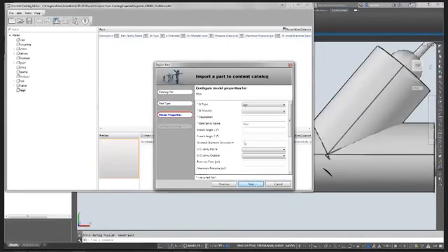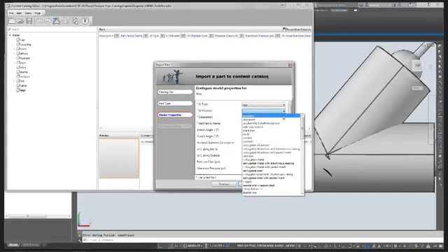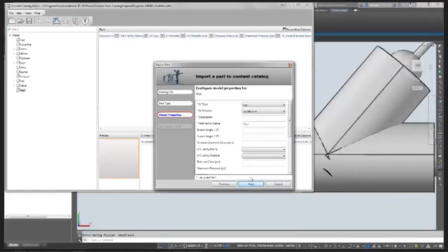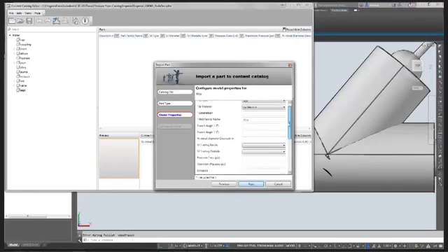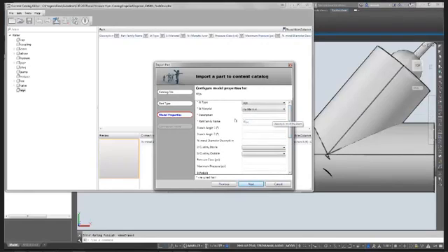Next, I can add information in here, the material. Well, typically it's ductile iron. Maybe it's PVC, maybe it's HDPE, whatever. Though the issue I have on this is my material says ductile iron. Well, I don't want it to say ductile iron. I want it to say DIP. Unfortunately, you cannot change ductile iron to be DIP here. You have to change it down in a different spot.